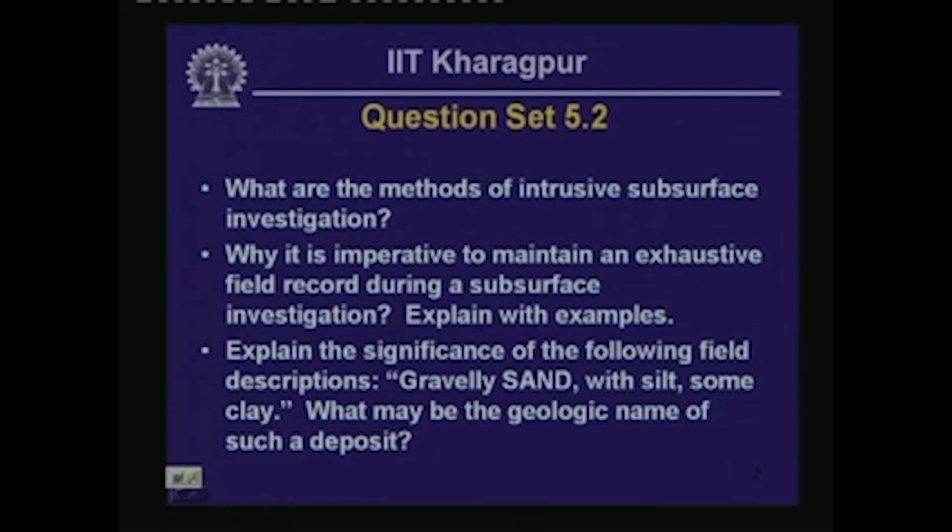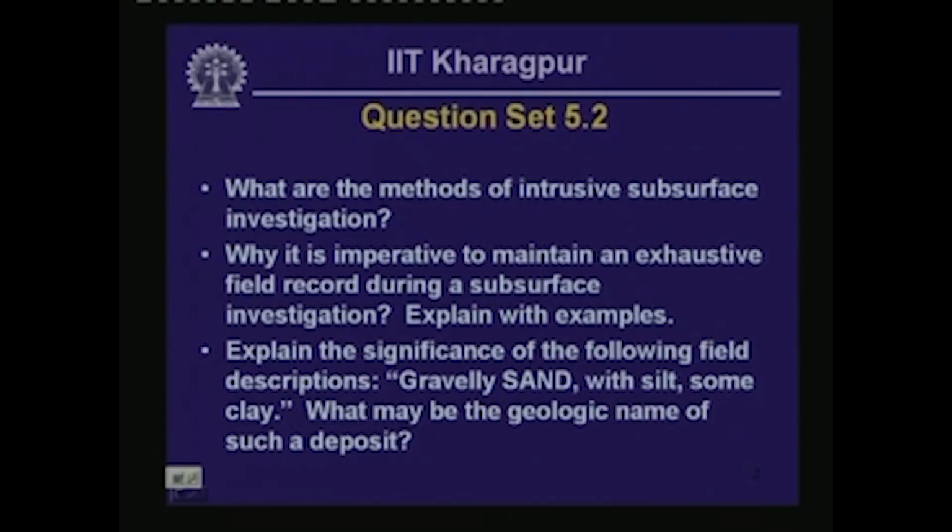Now as soon as that description is seen by a user of the drill log, what he or she has in mind is that this particular sample contains a very large proportion of gravel and sand, and it also has some percentage of silt and some percentage of clay.